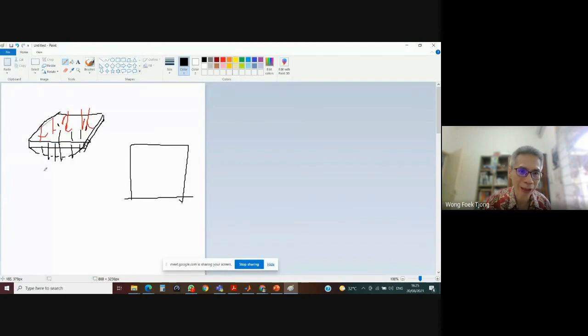How do we discretize using finite elements? We choose in our software, for example, to divide this into several quadrilateral elements, like this. Then these are the finite element nodes, let's say four nodes per element. Each element has nodes. What does it mean, nodes? Nodes are the locations where we define the finite element displacement.